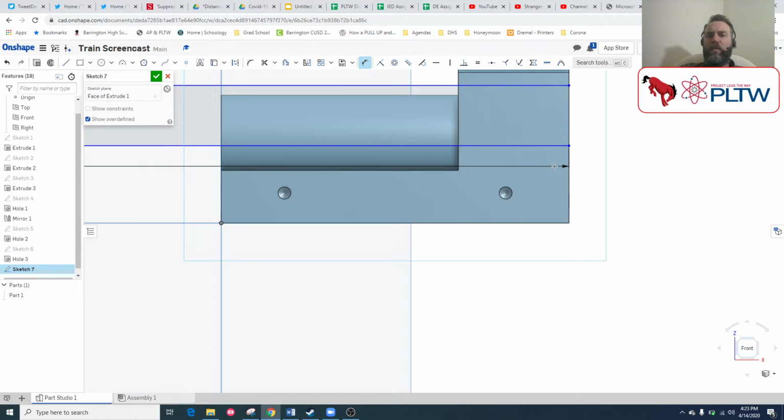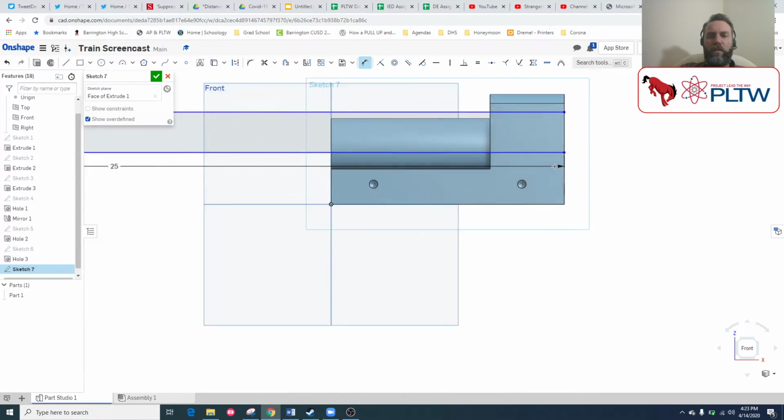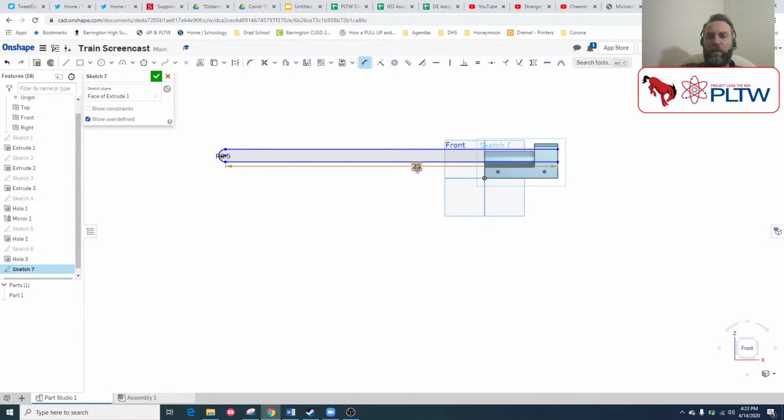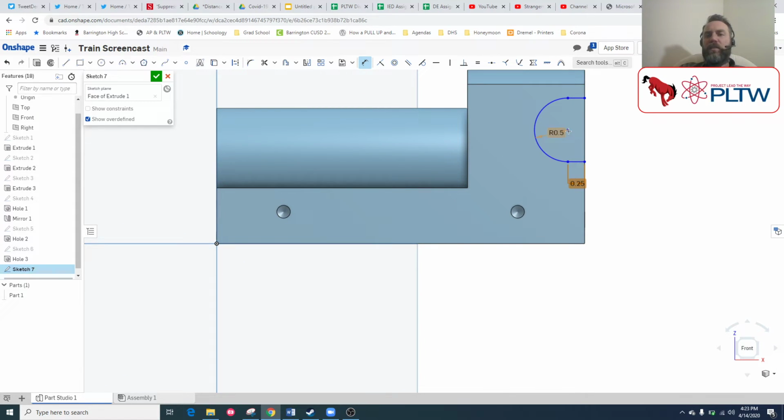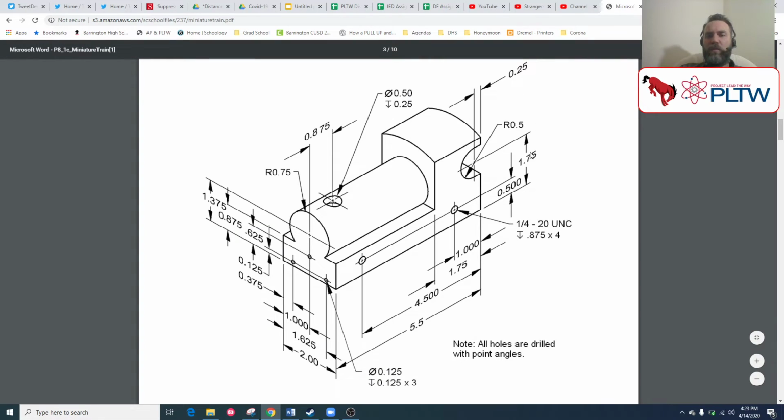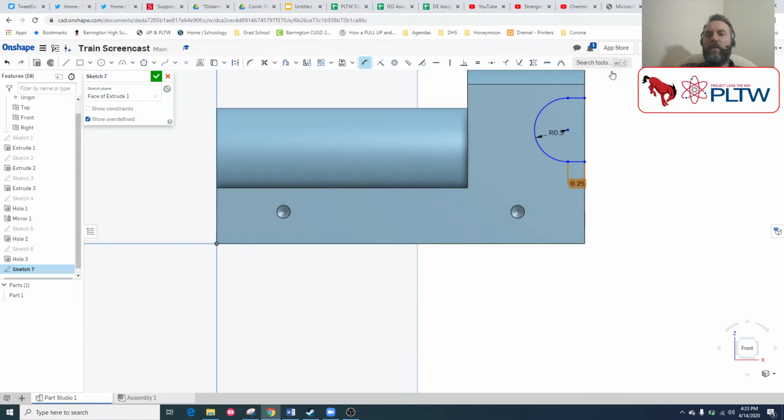I need to get, what did I just type in? Where I typed in 25. 0.25. That looks a little different. I need to figure out where the center is located, in terms of height. I did not grab that. It's 1.75 off the bottom edge. And then I can extrude that just through all. We're pretty close as it was, 1.75. Not going to see much.